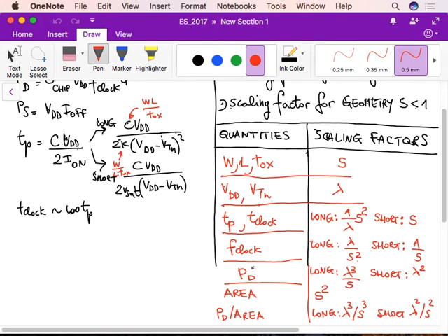But you decrease the power consumption of a single logic gate, and since you decrease the power consumption of the logic gate in the same way as you decrease its area, the power consumption per unit area remains constant. So you could keep the same power consumption per unit area while increasing the clock frequency, while increasing performance.